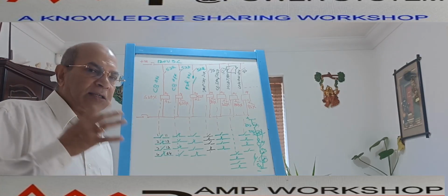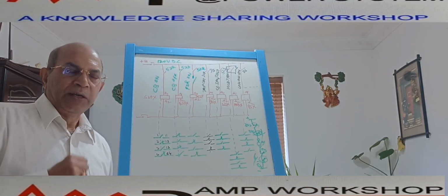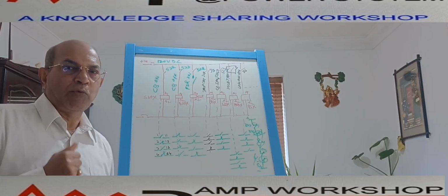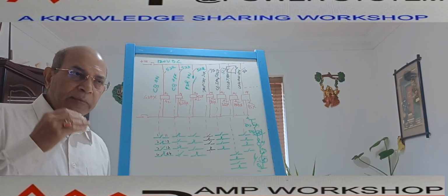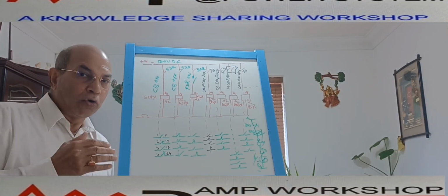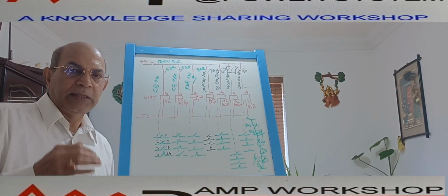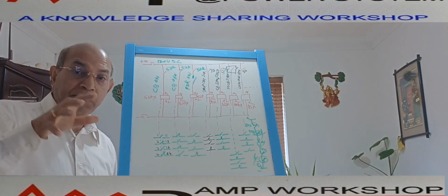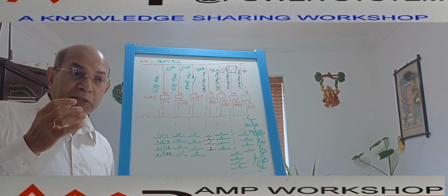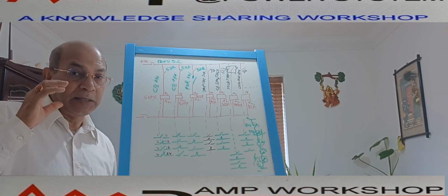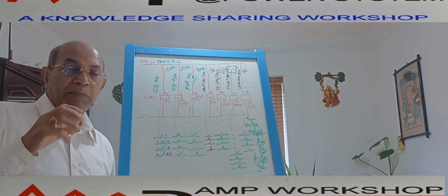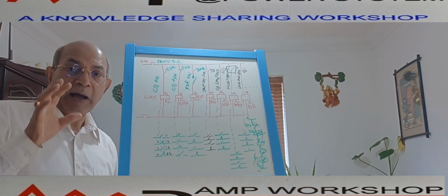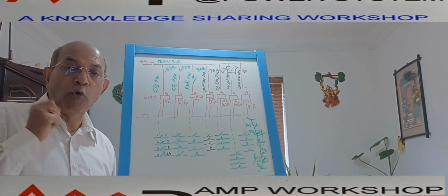Similarly, suppose there is an SF6 circuit breaker. In the SF6 circuit breaker, the SF6 pressure is continuously monitored by pressure switches, a low switch and a high switch. There are 3 pressure switches inside the SF6 chamber. If the pressure is very low and the breaker operates, the trip coil trips the breaker, but the arc may not extinguish due to the low pressure.